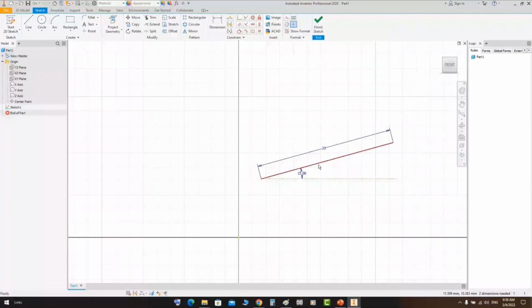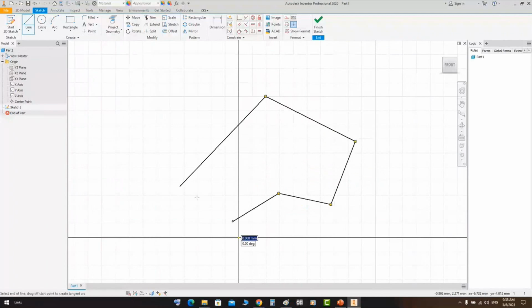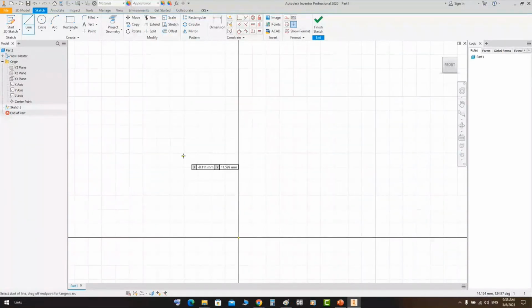That's the second way to generate or create a line. The first way, which we discussed, is by defining the start and end point roughly like that. When you select a line by Tab, you will be able to define the start point, and define the length and angle. Okay. Now let's add a line. Let's know one more option for the line, which is making an arc tangent to the line from the end. The line command can do that. How can we do that?